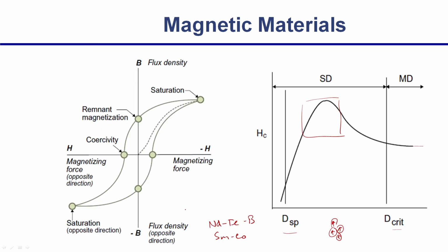And the last thing I talked about is, if you have small particle size like nanomaterials, what will happen to the magnetization, right. As you see, the plot shows the behavior above a certain grain size or particle size, whatever you call. Grain size is a better terminology. The magnetic moment remains the same, or the coercivity here is plotted. The coercivity remains constant, but below certain values of the grain size, coercivity starts increasing rapidly.